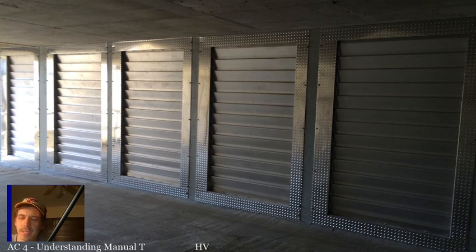So it only takes a small amount of airflow drop at that point to be enough to trigger the fire damper, the fusible link in a fire damper. So remember too, pro tip, because I don't think we really discuss it, I don't know if we get a chance to go over any code in this class, but a fusible link in a fire damper is allowed to be set at 50 degrees higher than the normal temperature in the system.